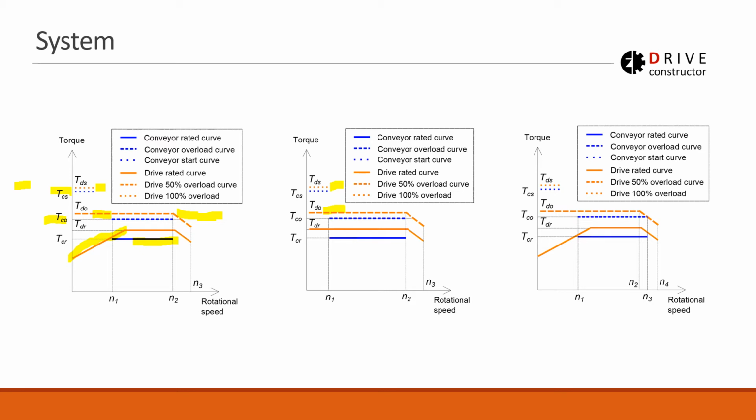The second thing that this diagram is showing is that we can have different cases depending on the cooling solution for our motor. Here in case number 1, we see the torque capability is reducing with reduced speeds. This is because this particular motor is cooled with a shaft-mounted fan. If we have independent cooling, then our allowable torque curve of the system starts basically from 0 speed right at the rated torque.